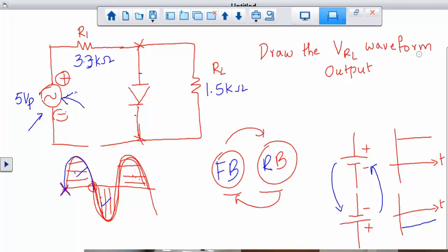Are we changing the AC source to go back and forth? That's the nature of the AC source, to go back and forth. So we're not controlling the AC source. When you say AC, it does it automatically. We're not touching the orientation of the diode. This is still a positive clipping. It cannot make a negative clipper. This one itself is a positive clipper.